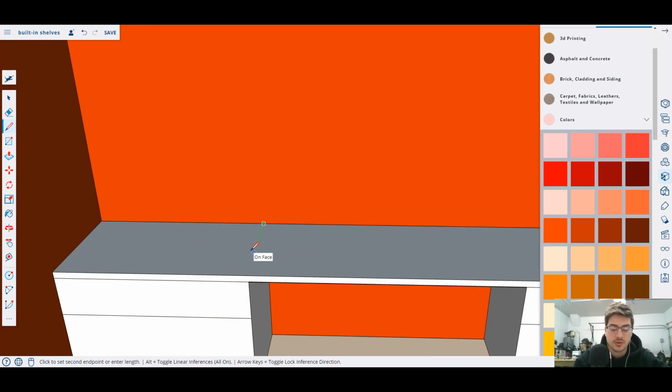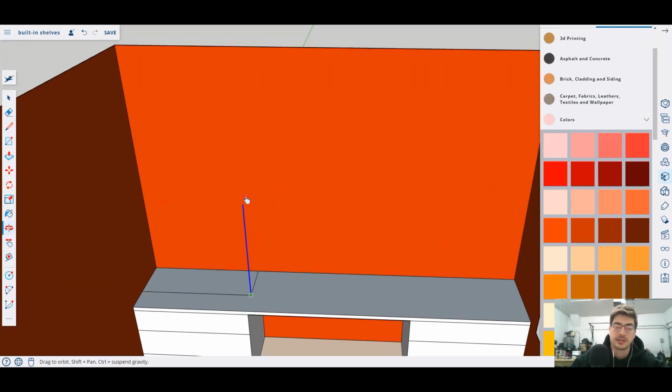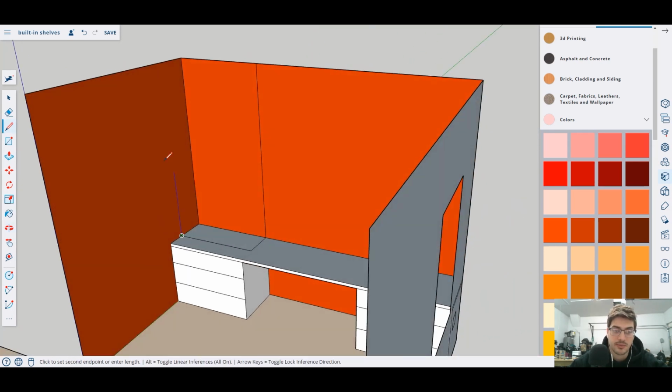Okay, and what we're going to do is we're going to make the shelves shallower. We're going to make them 18 inches deep, which is actually, let's do even less than that. Let's make them 15 inches deep. So that's kind of standard bookshelf depth. If you just Google standard bookshelf depth, you'll see what various home construction companies and everything else suggest. And 15 is generally plenty deep for decor or books or anything else that you might want. So we'll do 15 deep and 42 inches wide, and these are going to be some pretty cool bookshelves.